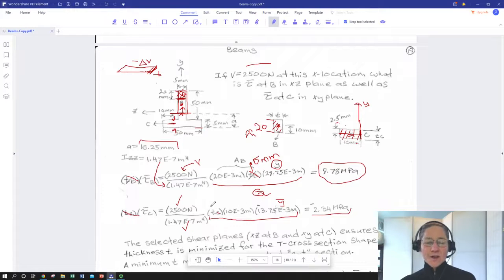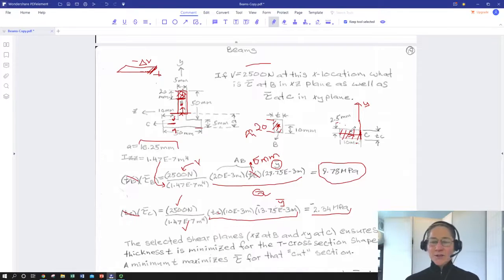So in this case, our area is not dependent on our particular position of where we put our cut line. We could put our cut line out here. Our area would be smaller, definitely, but our y centroid, our y bar, wouldn't change. So I guess I should have said it opposite. Our y bar would stay constant. Our area would be decreasing.